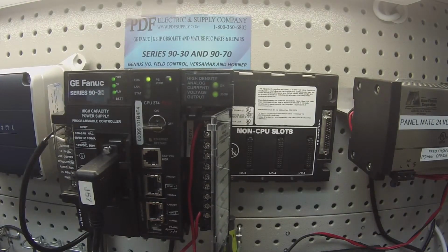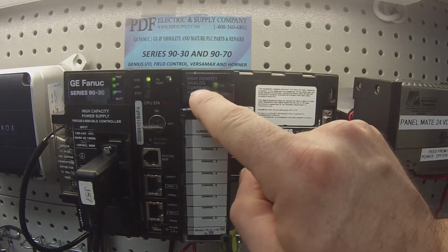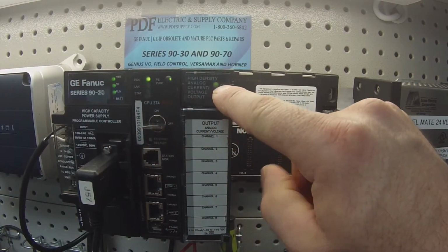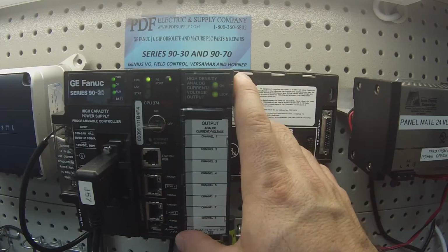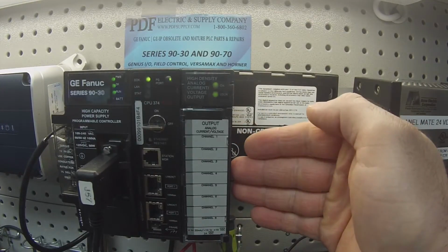Another thing that we commonly see with the ALG392 is a problem. There's a couple things actually. The first and easiest one is if you plug the module in and you turn it on and you don't get your OK LED. That's usually a very clear, quick indication that there's a problem with the module, and you normally wouldn't get any response from it.